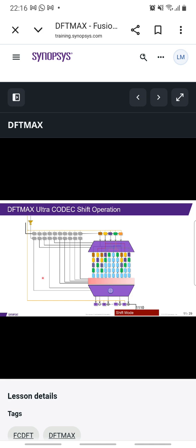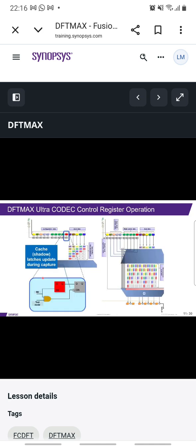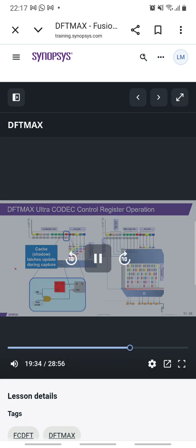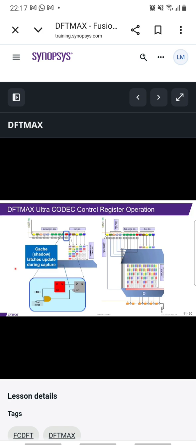Once the load-unload process has completed, the data left in the tail will become the next pattern's control and mask. So at the end of the shift process, the codec control is latched into some control registers. These bits get latched when scan-enable transitions. This includes the codec mode and masking information for the pattern. The mode control bits control the load mode of the next pattern. The mask control bits control the masking of the current pattern unload.